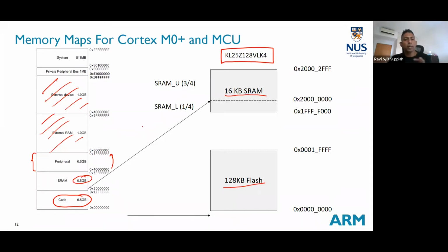For now, we take it that the hardware is already mapped for us with specific addresses on the KL25Z board, and we will use the mapping that is given to us. So we don't need to worry about any of these specific addresses for now. But we will look at some of these addresses later on as we look at the peripheral subsystems, just to relate back to this memory map, so you can see how it is all linked together.